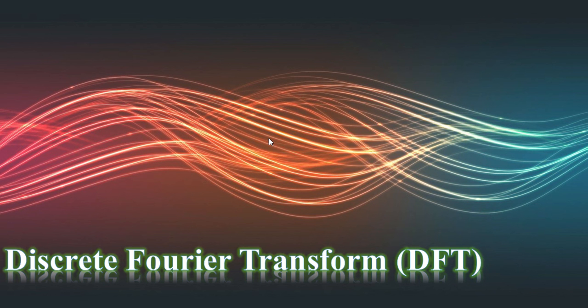So whenever we try to calculate DTFT at discrete values of my omega, we know that the total range of omega is moving from minus pi to pi, and basically if you sum it up, it is 2 pi. So if omega is sampled at n points, then there will be 2 pi by n spacing, right?